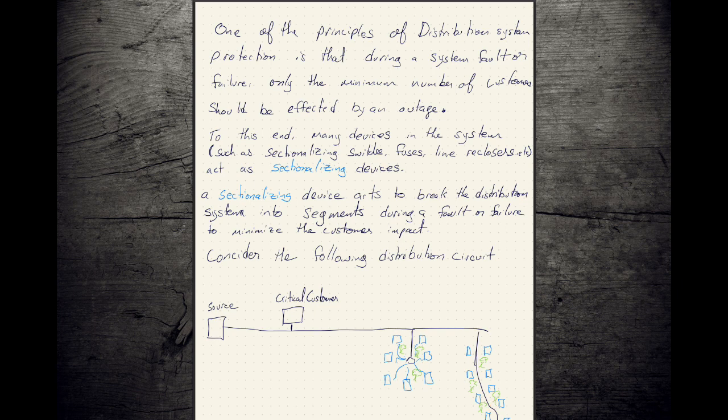And you take off down the main line and you turn onto the side street into the residential area, and all of a sudden, the nature of the area you're in changes. There's trees all of a sudden. There's squirrels. Sometimes those trees are right up into your power lines. And so if you're going to have a failure, your failure is more likely to be in here with the treed area than it is to be out on the commercial thoroughfare where you don't have so many trees or other things in proximity to your lines.